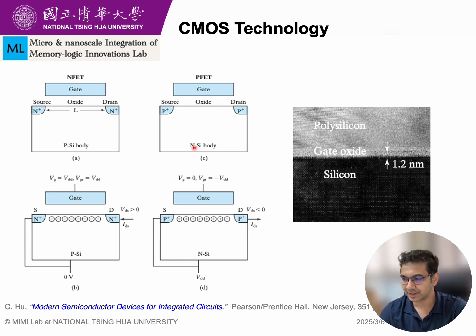I was doing SPICE coding and TCAD for almost a year, the first year of my PhD, and then fortunately I got the chance to work on FinFET development, and then I understood how difficult and how critical each parameter is. If you want to do bulk, you have to do more than 100, like 130 or 150 steps. If you're doing SOI, then it can be reduced to 60 steps.